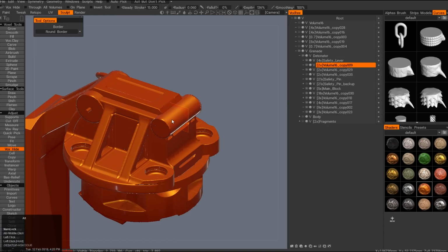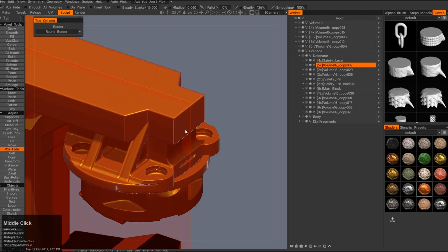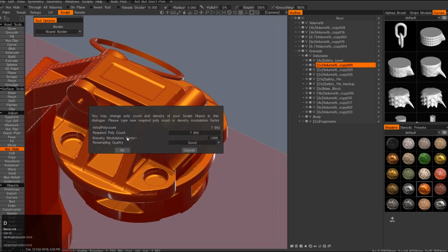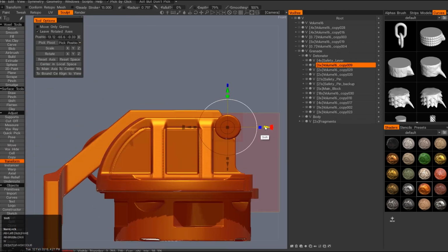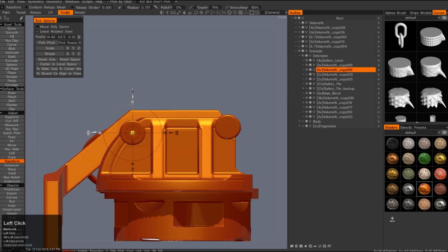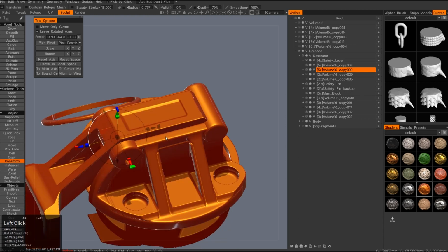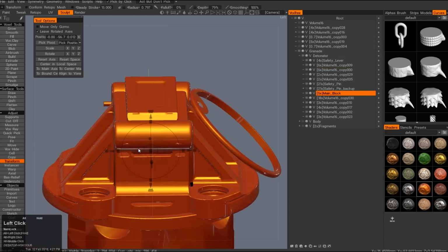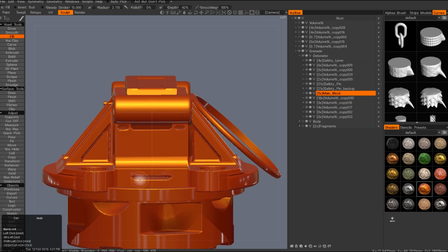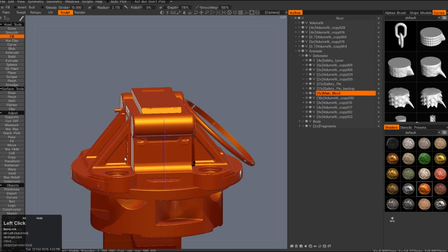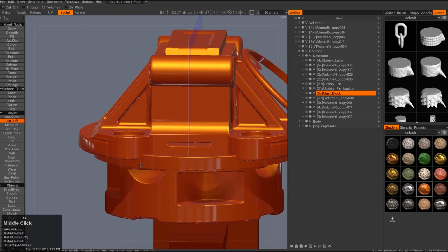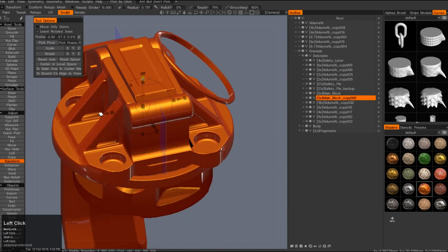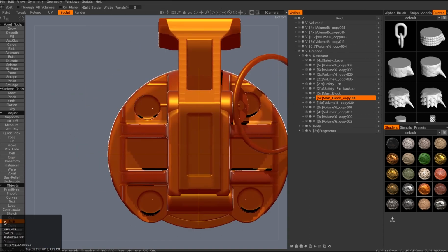You can see the straight lines here and there, on the detonator, the orange one, and that happened because I smoothed out the mesh while I still had some parts hidden. Then I decided to unhide certain parts, and when I hid parts, it starts to look like that, because you have a smooth mesh, then a solid unsmooth mesh that's been hidden, and you get those artifacts that are really hard to fix. I wasn't able to fix them all in the end. It's not really noticeable that much in the end of the day, but it is annoying.